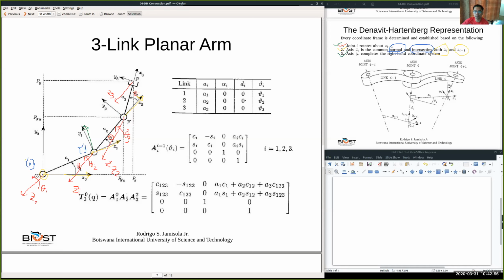So now let's finalize our frame 2 origin. So that is our frame 2. Again, once you identify the X2 axis and Z2 axis, you already know the origin of your frame 2, and now you know where Y2 will be to complete the right-hand rule. Again, that is Z2 coming out, X2 is in that direction, and so Y2 will be in that direction for the right-hand rule.